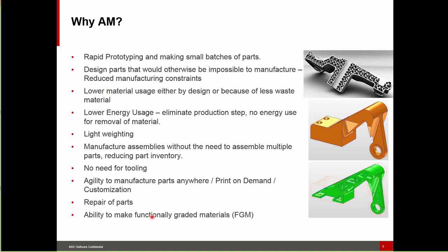So why additive manufacturing? A lot of this came out of the world of rapid prototyping. Additive manufacturing allowed us to make very efficiently small batches of parts. And the reason for that was additive manufacturing does not require tooling. So you don't need to build dies, you don't need to set up new hardware. So if you're only interested in a few pieces, additive manufacturing was very beneficial. Of course, one of the things we want to do is move from rapid prototyping in few batches to more production orientation.